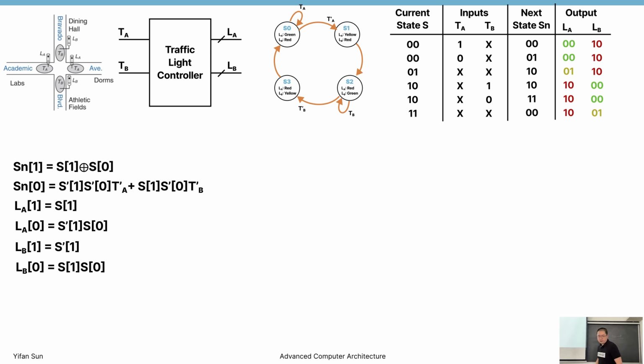Okay, so at this stage, let's give a quick overview of how we arrive at this stage. We have the problem, we have the symbol, we define the input and output, we list all the possible combinations of output. Then we consider each possible output as one state, right? We define the state, there are 4 states. Now we summarize how this state can flow from one state to another. What's the principle? What input triggers state transition? Then we write down this state transition table.